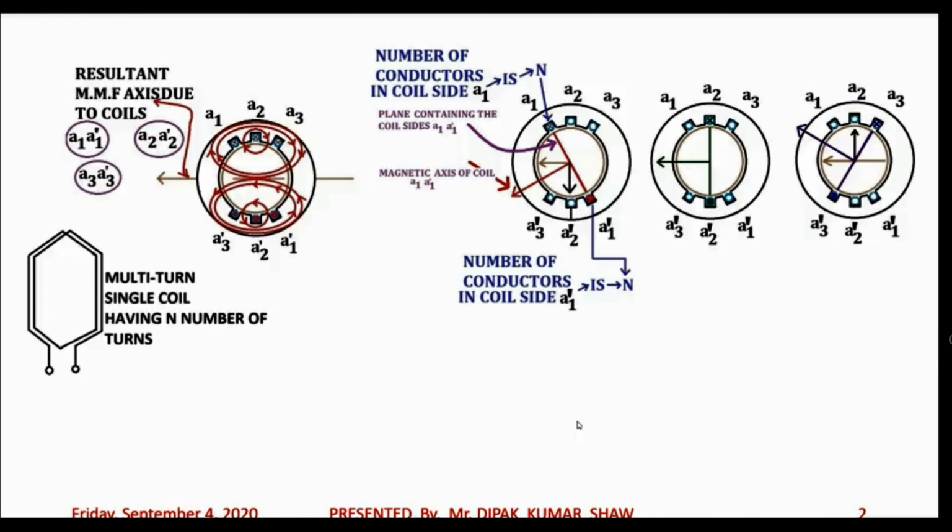So when I have said that particular line, that the MMF in the air gap of a single phase induction motor is stationary and pulsating, there I have made that assumption that the single phase induction motor is having only one winding energized. That means only the main winding is energized. Even though there can be an auxiliary winding, that auxiliary winding is not energized. So this point is very important, otherwise that will lead to a confusion.